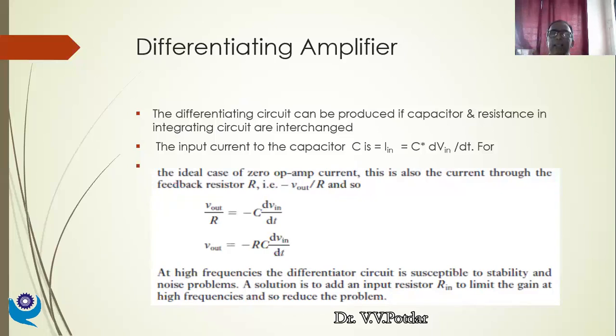Maybe considering the same case of a temperature control system, furnace temperature control. What I am getting as output now is from observing the past data for 1 hour. What was the rate of change of temperature? It will be projected as the rate of change of voltage, because the temperature is converted into voltage by a thermocouple. Say the rate of change of temperature was 10 degrees per minute.